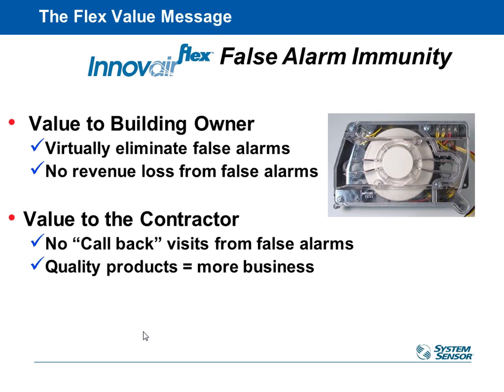We mentioned the false alarm ability by being able to adjust himself for the amount of dust in your ambient air. This does help out quite a bit. Every time you get a false alarm on a smoke detector, whether it's a duct detector or a ceiling detector, that just trains the occupants that it probably isn't real. I probably don't need to do anything. And obviously you get enough of those and people aren't going to respond to them, and then bad things could happen when they don't respond to a real situation. So you want to eliminate those false alarms.